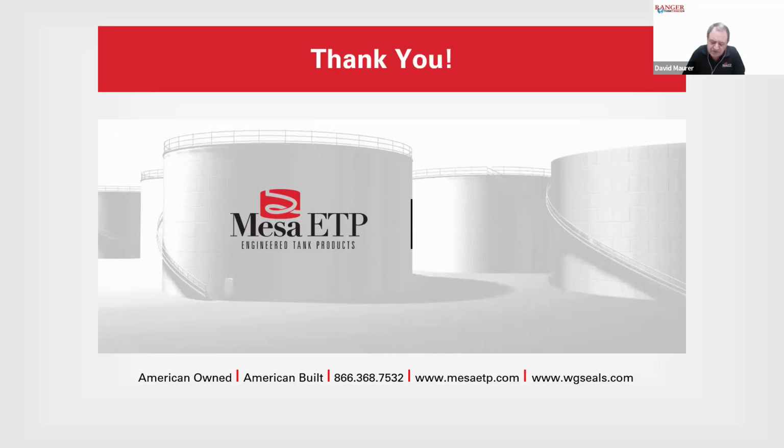Well, again, it's a function of trying to keep the wind out of the equation on an external floating roof. I've never seen it, but I believe New Jersey has an edict that if you've got a floating roof with a leg in it, it better have a sock on. The socks, I believe the EPA gives you a credit for having those socks on to the tune of about, I want to say it's like 65%. And I've had an argument with them before about where the other 40 is coming from, because it's perfectly sealed off.